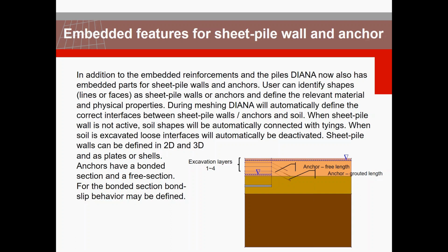And after activation of the sheet pile and the corresponding interface, you can proceed with the excavation setup in the program. When you deactivate the soil layers, for instance, you go through the level of excavation, then it automatically also deactivates the loose or hanging interfaces. So in terms of data management, in terms of activate and deactivate, as a user, you're dealing with minimal operation.